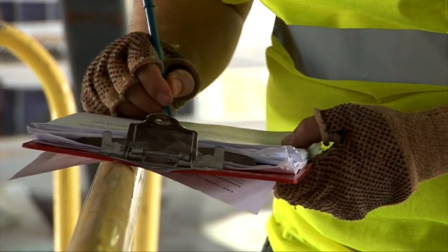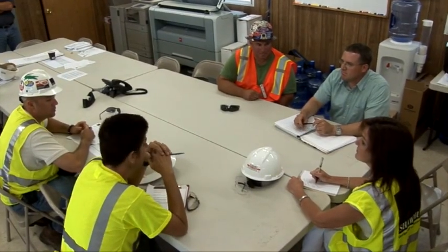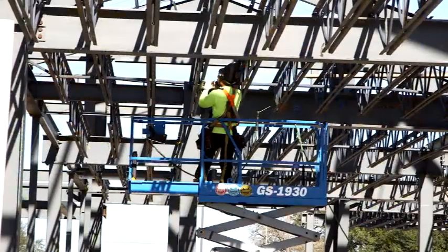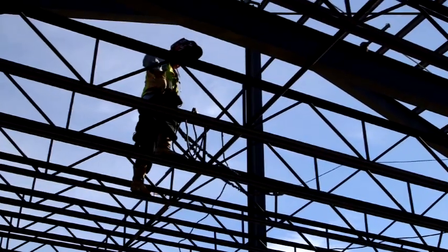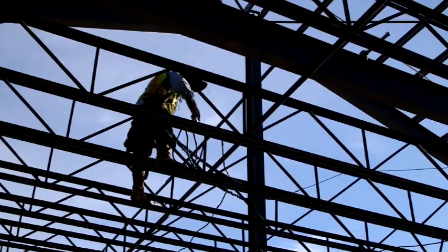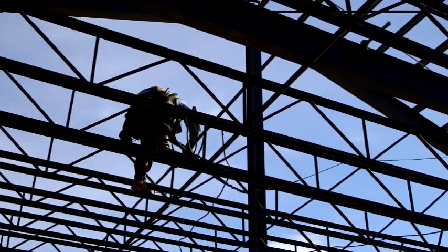Employers must prepare current written certification to show a record of each employee trained and should include name or other identification of the employee trained, the dates of training, and the signature of the employer or the person performing the training. Employees should also be retrained when changes to the workplace render previous training obsolete, when changes in the types of fall protection systems or equipment to be used change, or the employee's knowledge of use of fall protection systems or equipment indicates the employee has not retained the required understanding or skill.